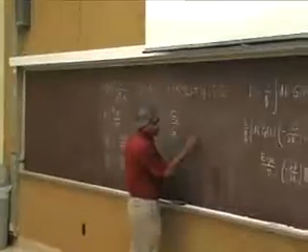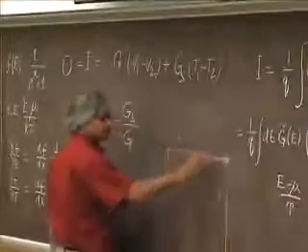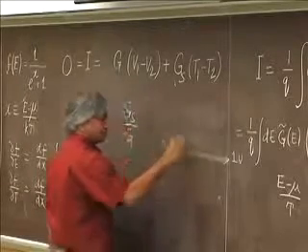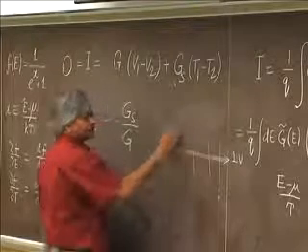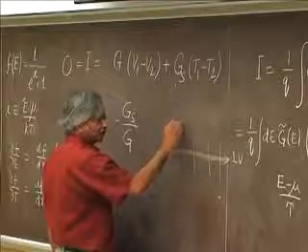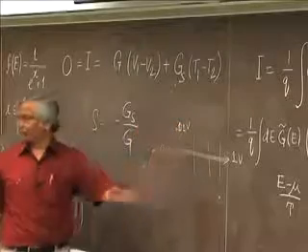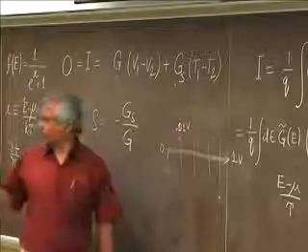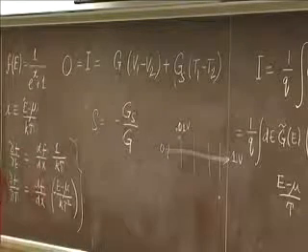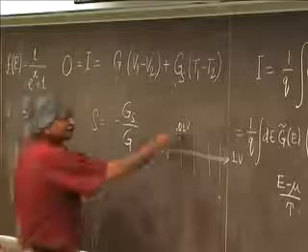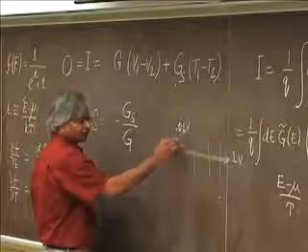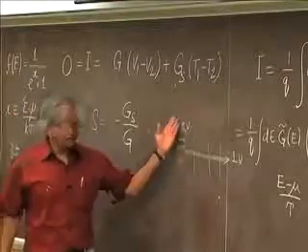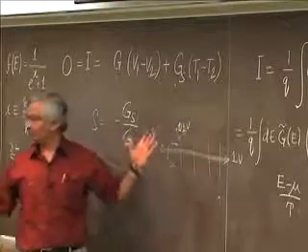so if you had a long series combination of lots of things, say this end is 0 and this end is 1 volt, and you're breaking it up little by little. And in one of these sections, let's say you have put 0.01 volt, because you had hundreds of these. So the point I'm making is that when you are trying to find the conductivity of this bulk material, you'll assume this much voltage and find what current flows, and you'll take the ratio and extract a conductivity.